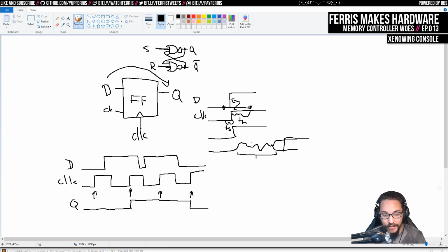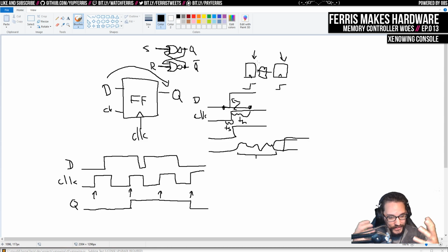And so timing analysis is really important when you're designing these circuits, and it's why you get such weird, non-deterministic behavior if you don't meet timing. But the nice thing is that it's pretty simple between a set of flip-flops, where you have this flip-flop here, and this goes into another flip-flop, and you have some logic in between. You know the setup and hold times for here, you know the setup and hold times for here, you know when these clock edges are going to arrive at each one of these registers, and so you can figure out how far away these need to be and adjust that. And the tools will do all of that for you, as long as you constrain your design properly.